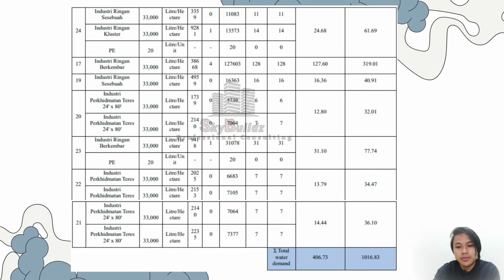If we compare this value to the northern region, we can see that this region requires less water demand since it has a lesser number of light industrial buildings compared to the northern region. From this value, we can already estimate that the value of residual pressure head for this region will be lower compared to the northern region, thus may require a lower number of water tank design, lower height of water tank design.